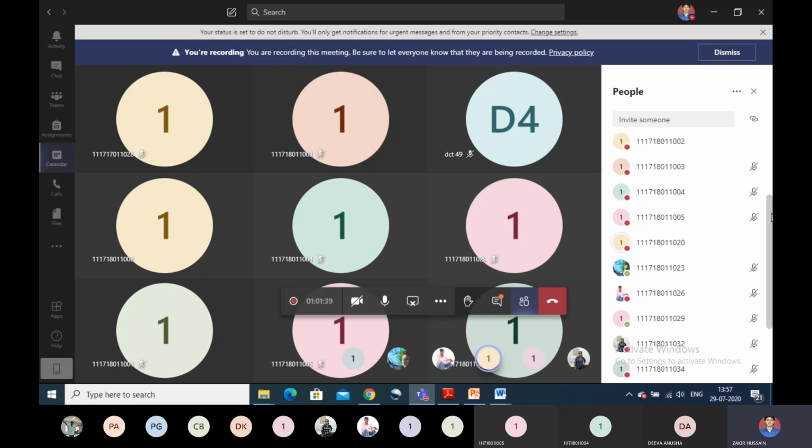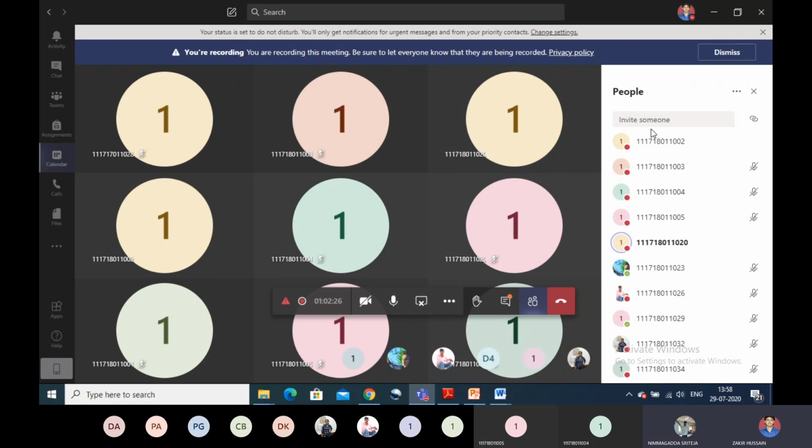Relationship between fluxes. N_A is equal to N_xA plus J_A. Hello. N_i is equal to N_xi plus J_i. Fick's first law of diffusion: J equals minus D_AB into dou C_A by dou Z. Where is D_AB?